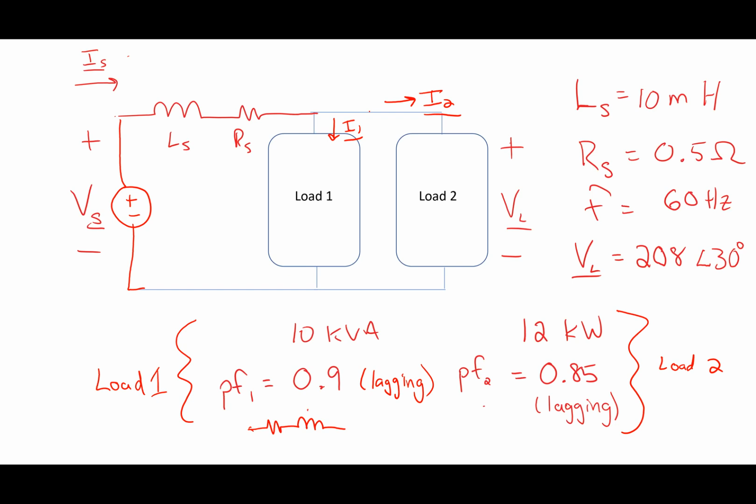Yes, there are transformers in the system for sure. But if I look at these loads, your house probably doesn't have any transformers. You're starting to think about the transformer stuff, which we'll talk about later. But what's the stuff you're plugging in? There's mostly resistive stuff, or motors. And what's a motor? A motor is iron and wire, which is an inductor.